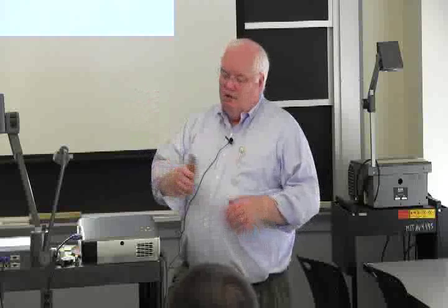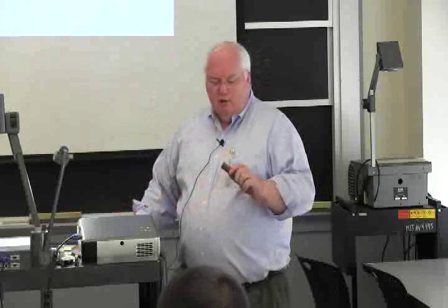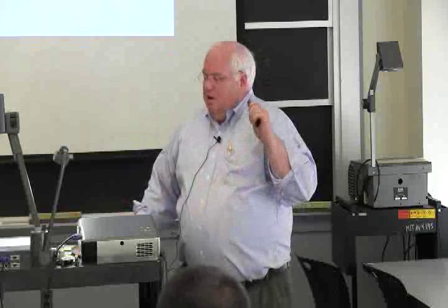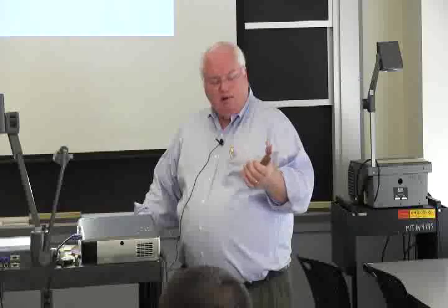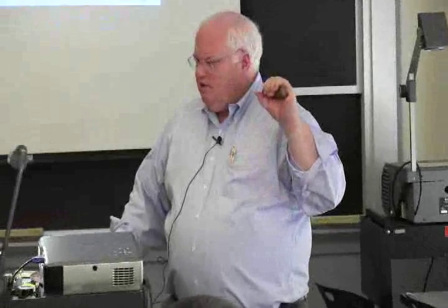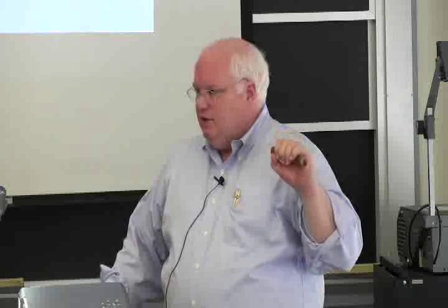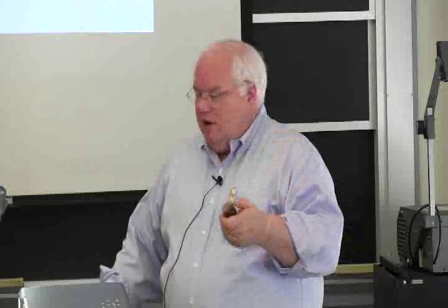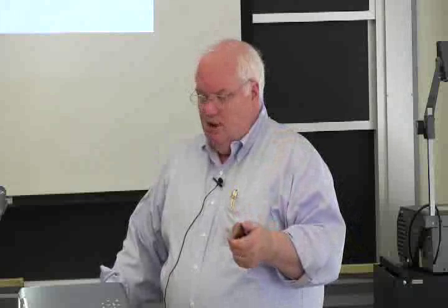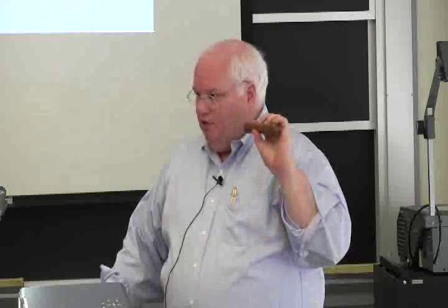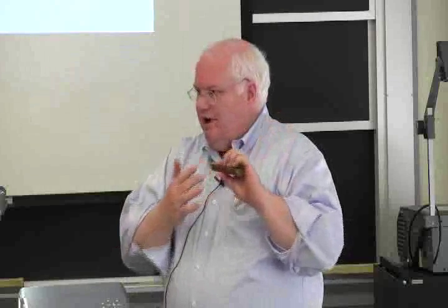This particular ingot actually has a very small amount of silver, like 0.1%. I was brought in because this was going to be the trolley wire for the Amtrak New Haven to Boston extension, the overhead line. And the company that was making this wire, the largest diameter wire they had ever made was 5/16 of an inch diameter. And they had made it from this 1 3/8. Now this starts out as a very large grain. This is not segregation here, but it's the grain size.